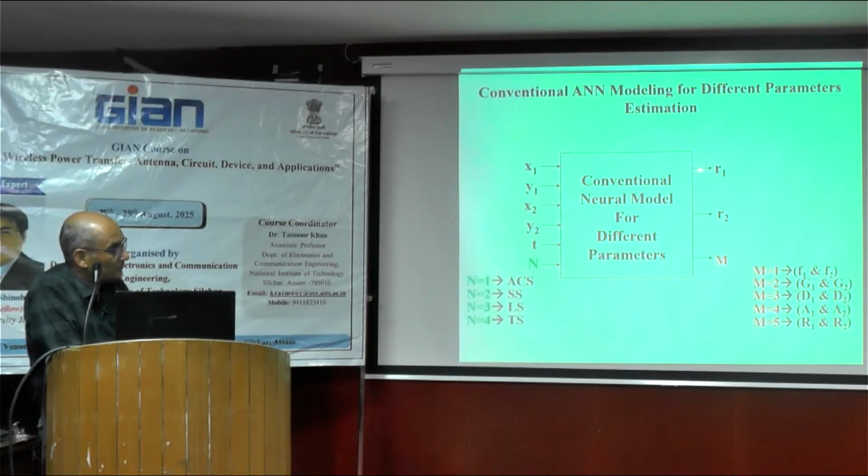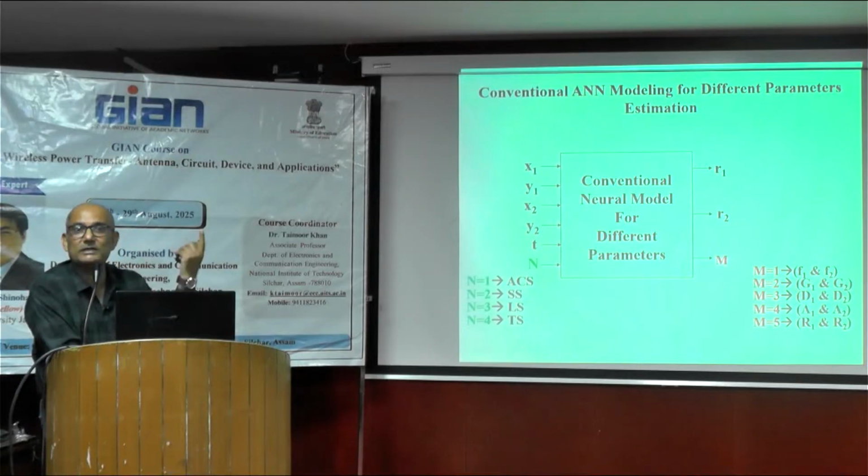These two points are to be differentiated for gain, bandwidth and so on, so one mode input is also incorporated here. When the value corresponds to 1, the response at these two points is dual resonance. If the value is nearby 2, the response at these two points is gain 1 and gain 2, the same for directivity, antenna efficiency, radiation efficiency. Otherwise, it would be difficult to predict which set of parameters the response at these points corresponds to.